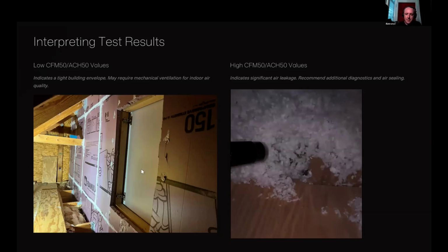We do have one more here. For heat pump water heaters ducted to the outside, doing a depressurization test, is it recommended to seal the supply side of the duct of the water heater? I've encountered some water heaters that don't draw air through the unit and others that are very leaky through various houses. Is this a byproduct of proper heat pump install or air barrier testing prep?